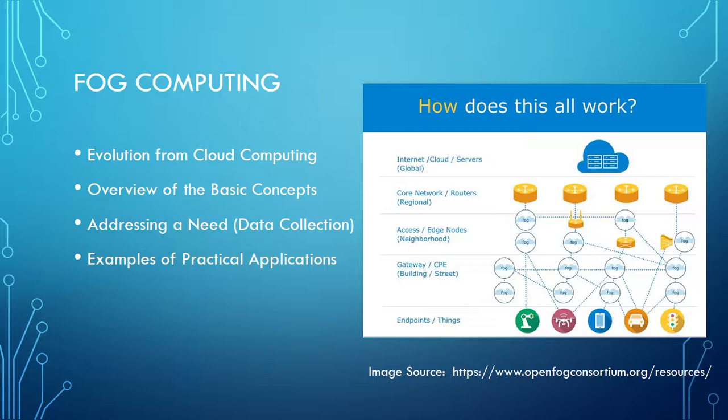Depending on the equipment requirement, some of the devices I've seen process about 10 collections per second, and depending on the network configuration, can be affected by latency. Latency is the time interval between when the data was initiated and when it was received. Data transmission through several layers of network devices has the potential to drop a packet or two. And if a switch went down and the routing compensated with a redundant path, potentially there could be a gap of data showing up in the data historian with some time and data loss.